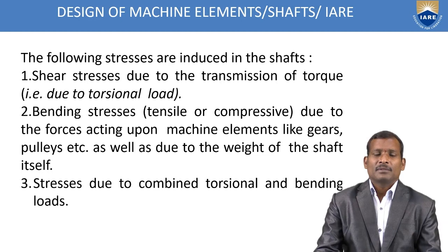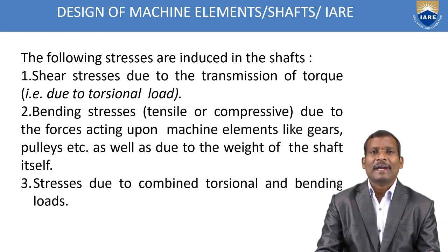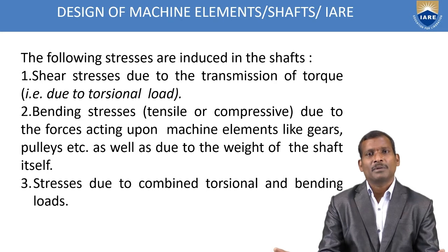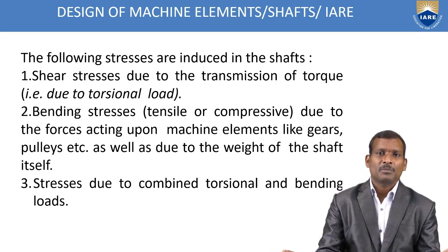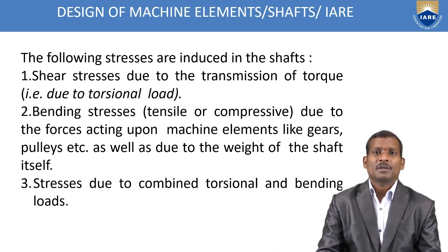For any design, first you should identify what are the forces acting on that element. It may be a gear, or a shaft, or belt pulleys, or couplings. First identify the forces and then calculate what are the stresses induced due to these forces.